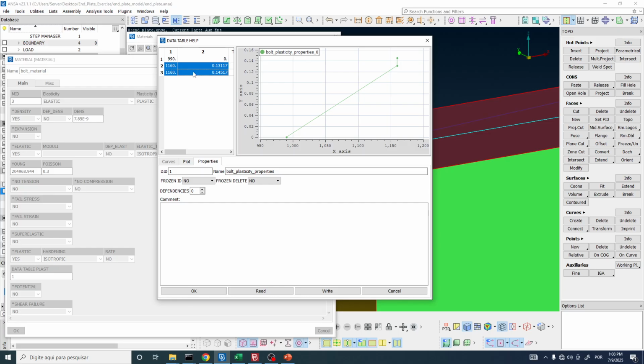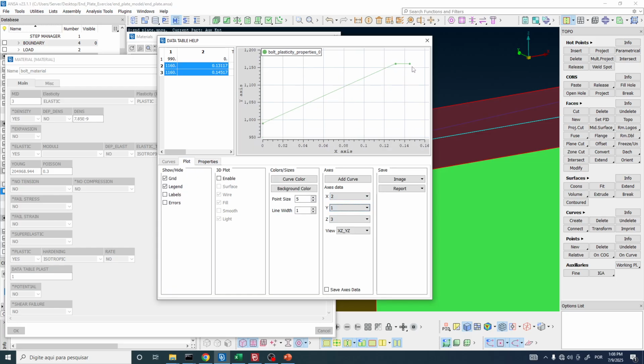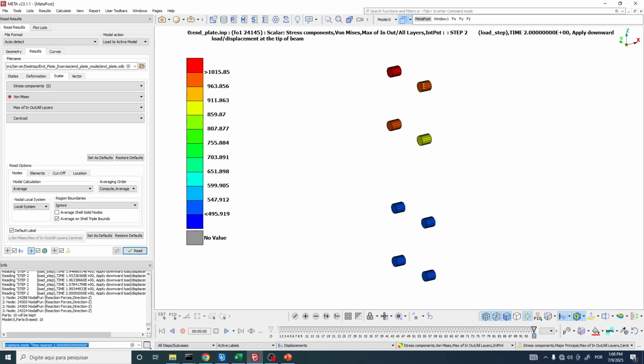If we had reached this stress, then the bolt would lose all its strength, because here we have this horizontal line. If we inverse here, we have this horizontal line, zero stiffness, and then we would have some instability occurring.